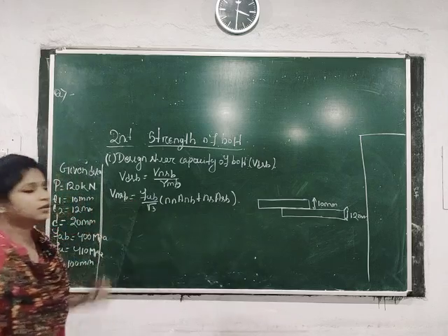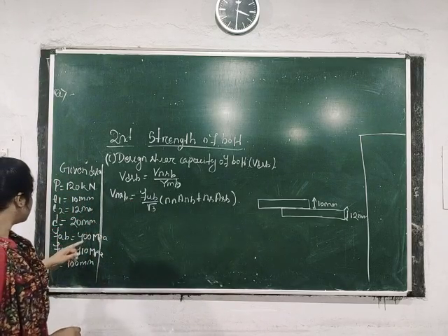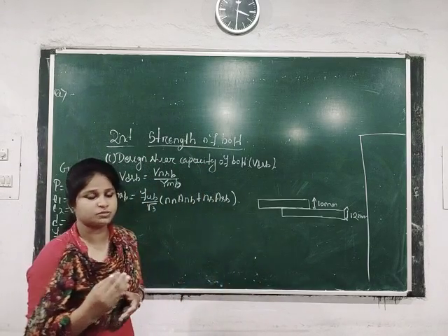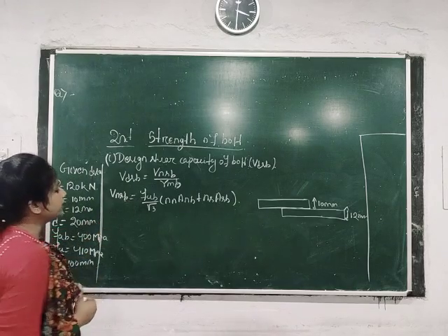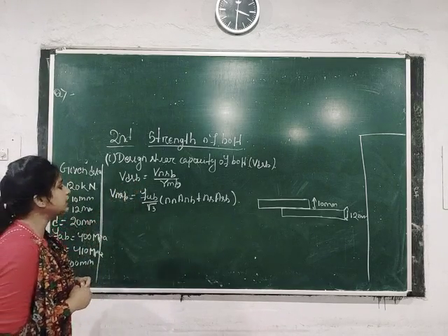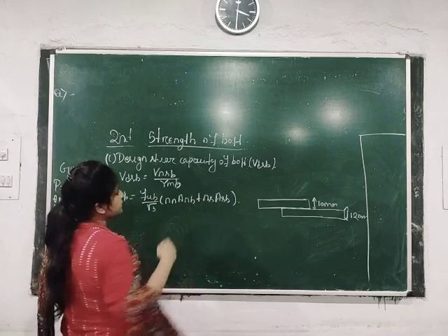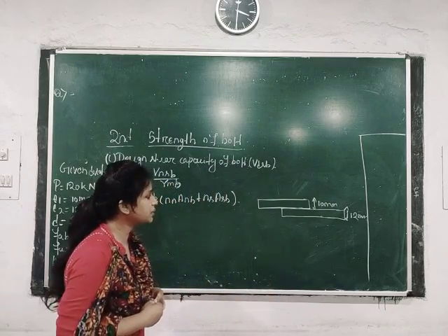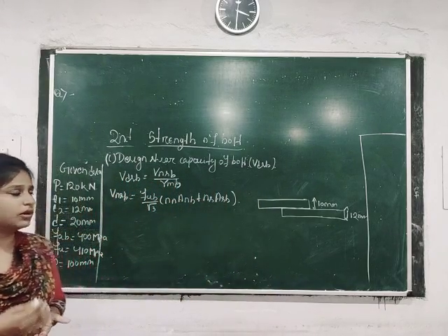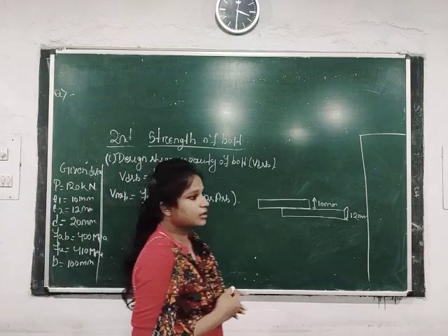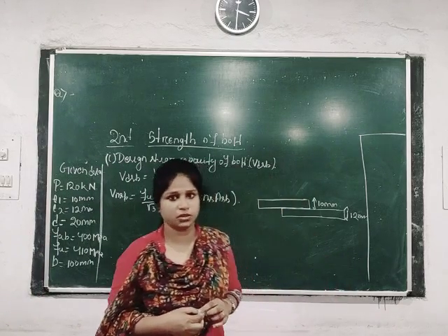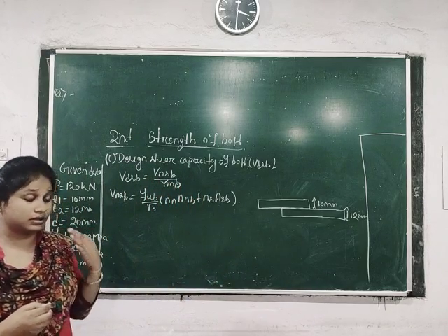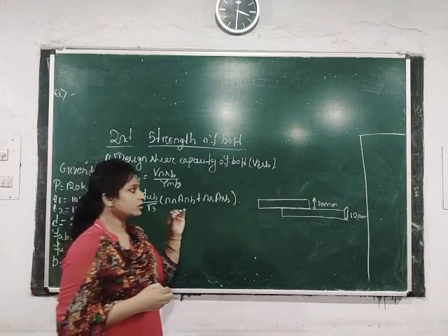Here the fub value is 400 MPa, that we got from the property class of bolt, 4.6. Then next come to nn and ns. As we are going to design the lap joint, and in case of lap joint, only one plane is undergoing shear. Lap joint is the case of single shear condition, and that plane is generally at the threaded part.